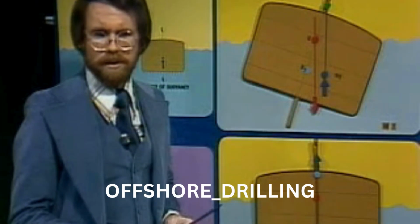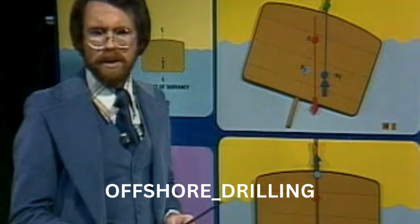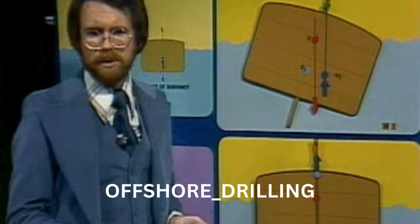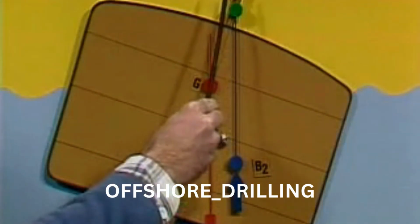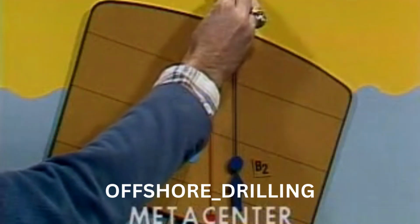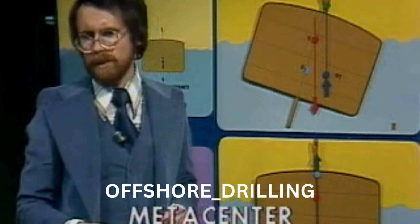As we said earlier, when the vessel is heeled or tilted by a wave, B will move towards the low side. It will move along the arc of a circle. The center of this circle is where the vertical line through B2 intersects the center line of the vessel. We will call this point the Metacenter, and we will abbreviate it as M. We'll talk a little more about M later on in the program.